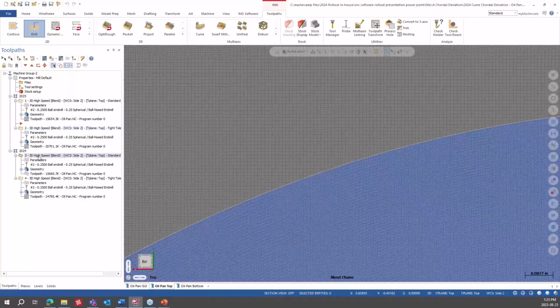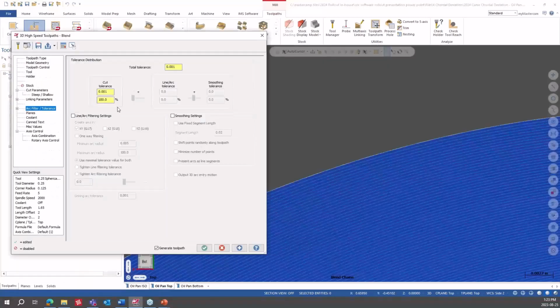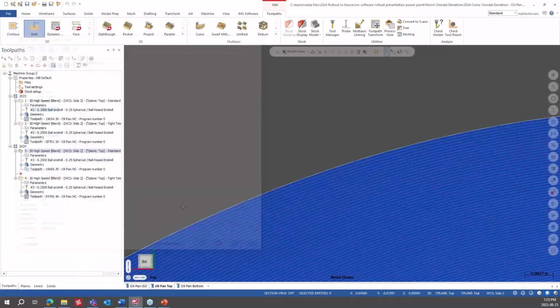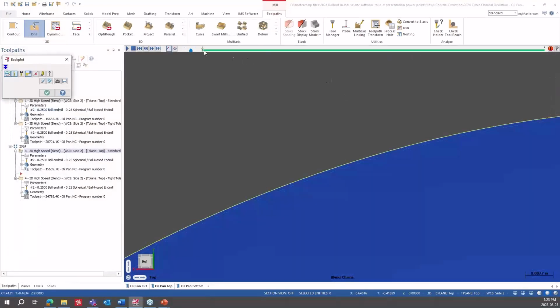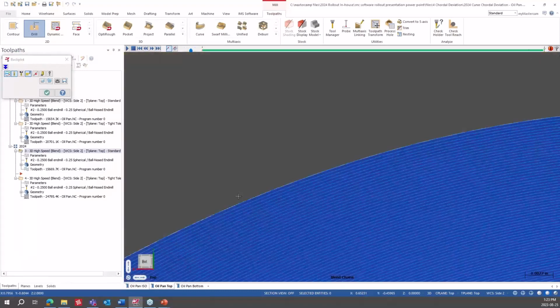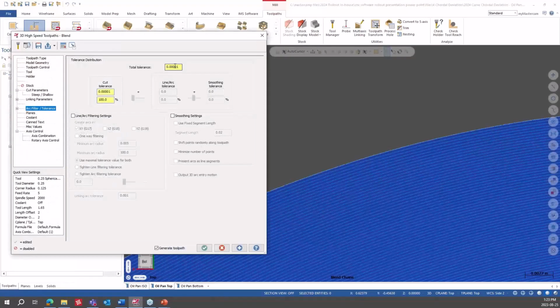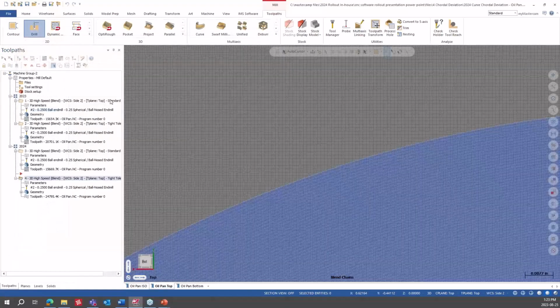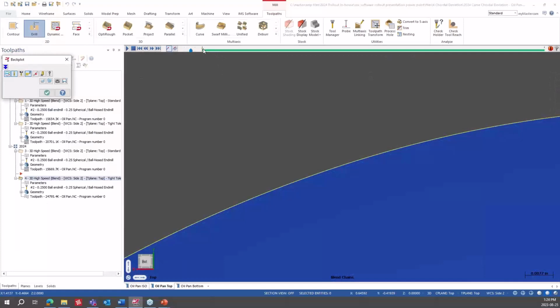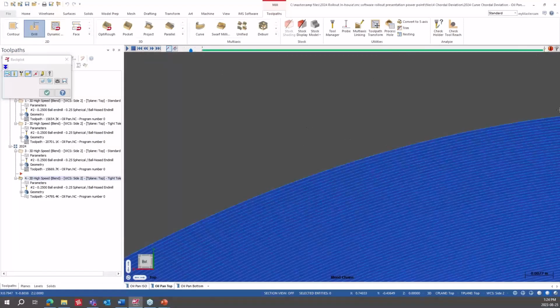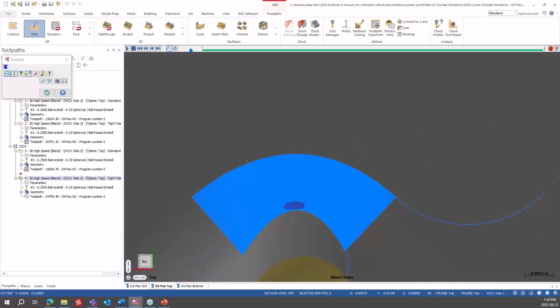So now what I did, I copied those two toolpaths down and recalculated them with the same 1 thou tolerance. If we look at this toolpath now, you can see how closely it's following that line. It's right there. You can only see some of the yellow coming through in certain areas. And if I wanted to go finer and do a 1/10 on that, I think that's set below. If I turn this on and backplot this, you can see just how close it's right on that line now. So this would become important for surface finishes, like maybe satellite customers and stuff like that. So this makes a difference.